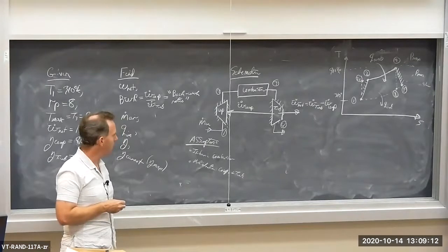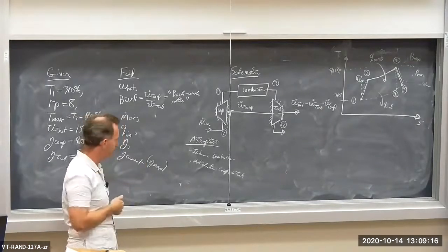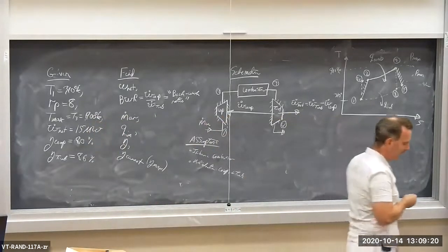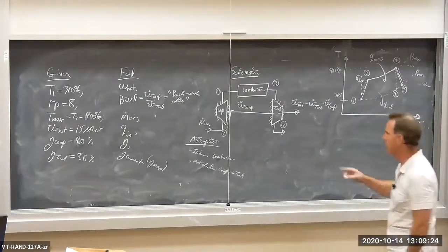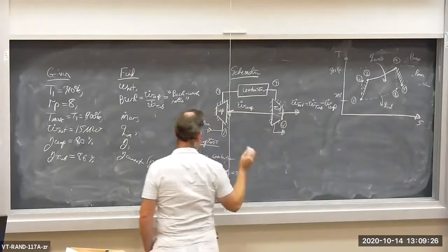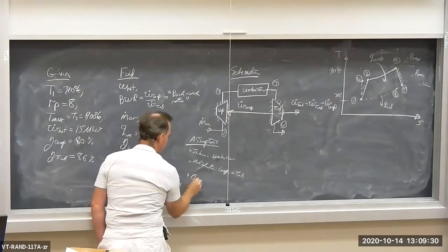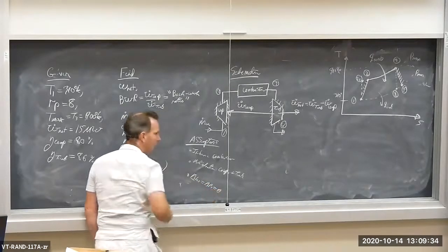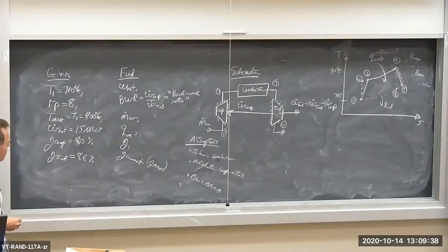Compressor work is positive, on the system, not by the system. And if I assume no changes in kinetic and potential energy, I got no information about kinetic and potential energy of any of the flows in this device. So I'm going to say delta KE equals delta PE equals 0 for every device. So I'm going to neglect kinetic and potential energy in the energy balance.